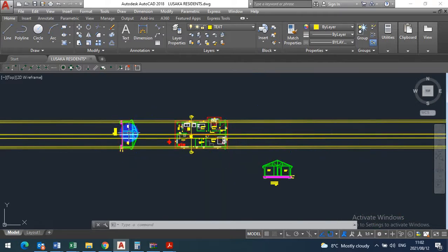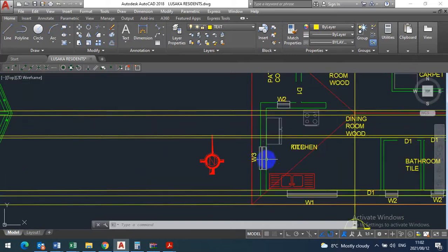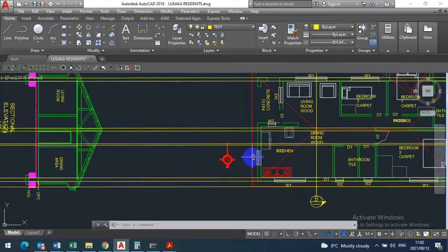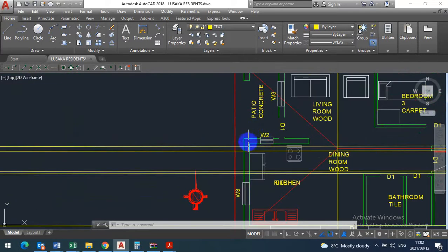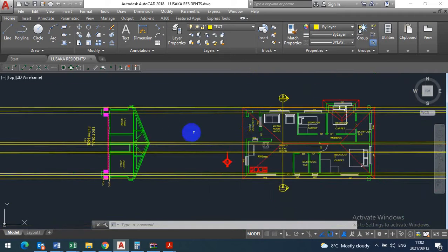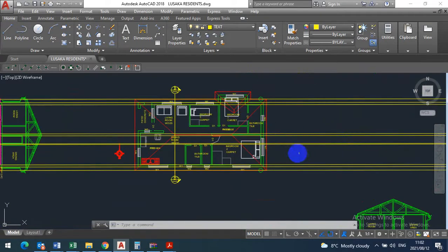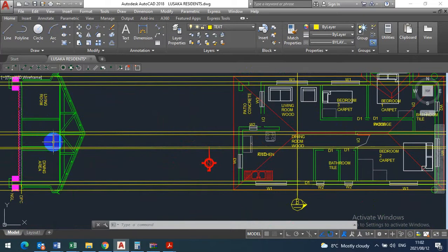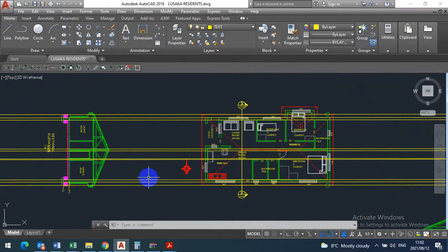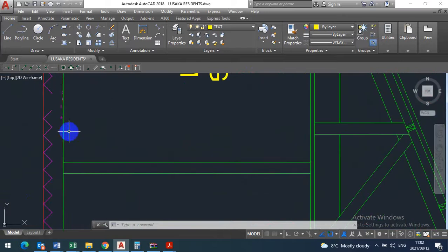The only thing I'm going to include here is the things I see outside, like window 3 is on the west. And on the west, there's an opening here. There's a patio. You can see this has an opening here. So there will be 2 lines here. Then on the east, it's going to be a mirror image like that, but without the truss, without the internal wall, without this door, without foundation details, nothing. On elevation, we only indicate the finished floor line, which is, let's delete that.